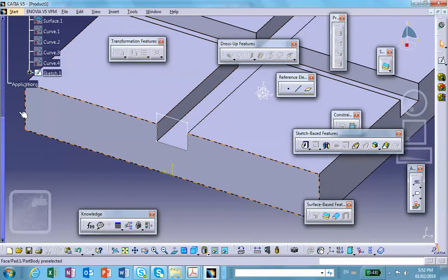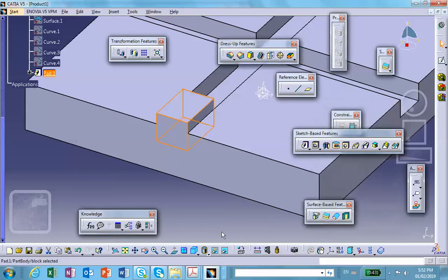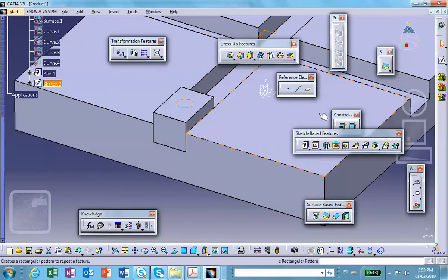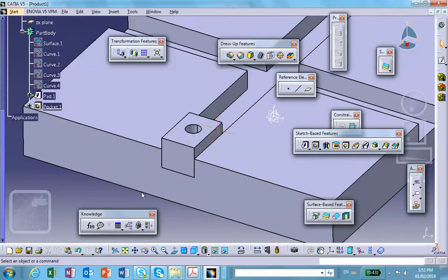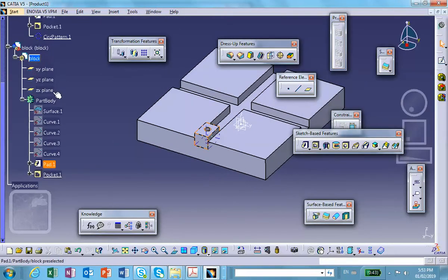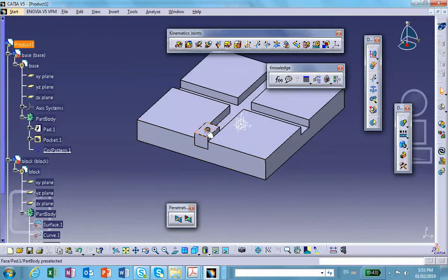Yeah, that's good. And on top of it, I'm going to draw a circle. That's where the pins for the rods are going to go. And you can always center it too, but I'll just leave it the way it is. Exit. And make a pocket. Alright. Good. Now, the other block is exactly the same size, same shape. So that being the case, what I can do is save everything and use an instance of this part. Or you can make it again if you want.